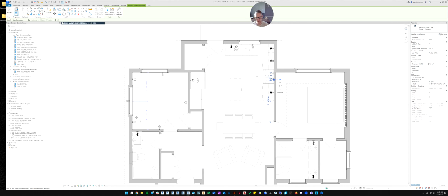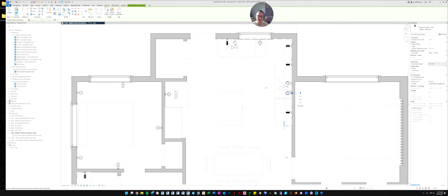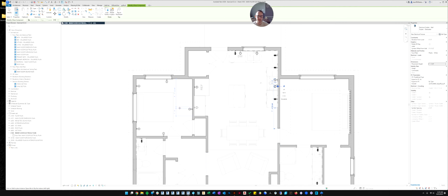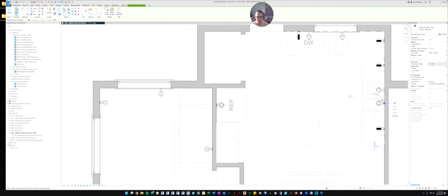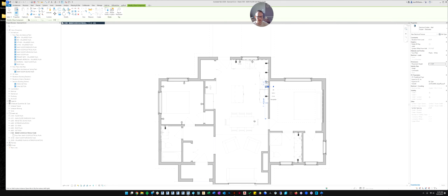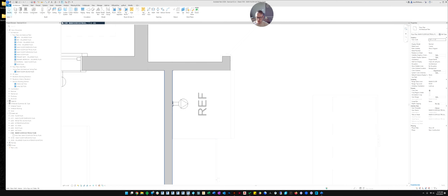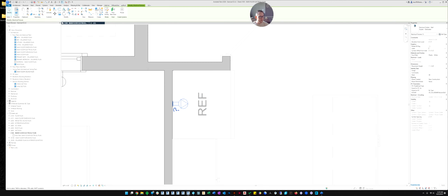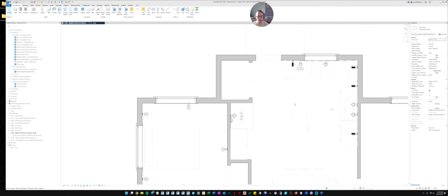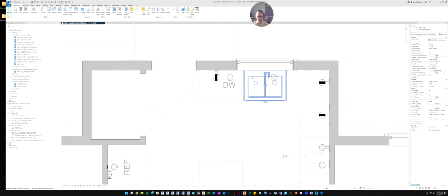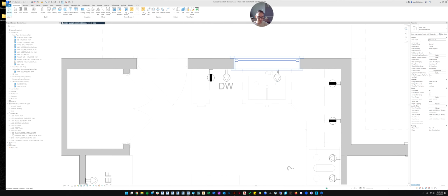Whereas in the rest of the house, maybe in one whole room, all the outlets in the room are on the same electrical circuit. Bigger appliances typically need their own dedicated outlet. So that's what this little triangle symbol means, that it's an outlet just specifically for one thing. And with these families, you can select the outlet, and there's something called a label over here. So you can label it so that the electrician knows what the outlet is for. You can do an abbreviation like refrigerator, or this one. It might be confusing to someone what that outlet is for.